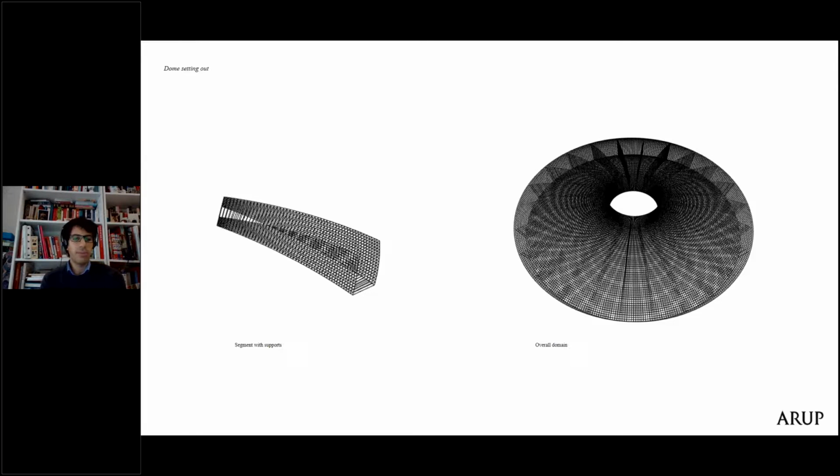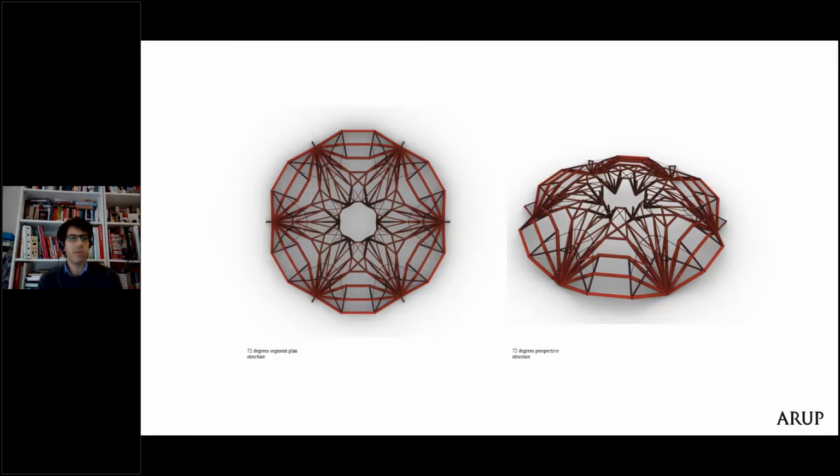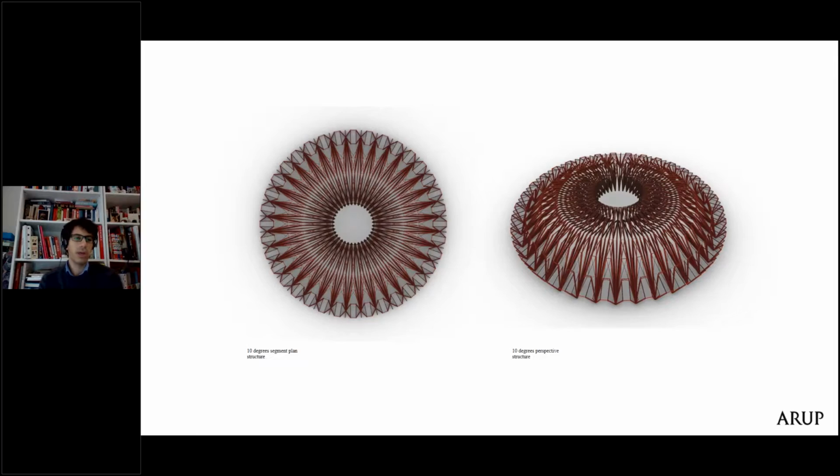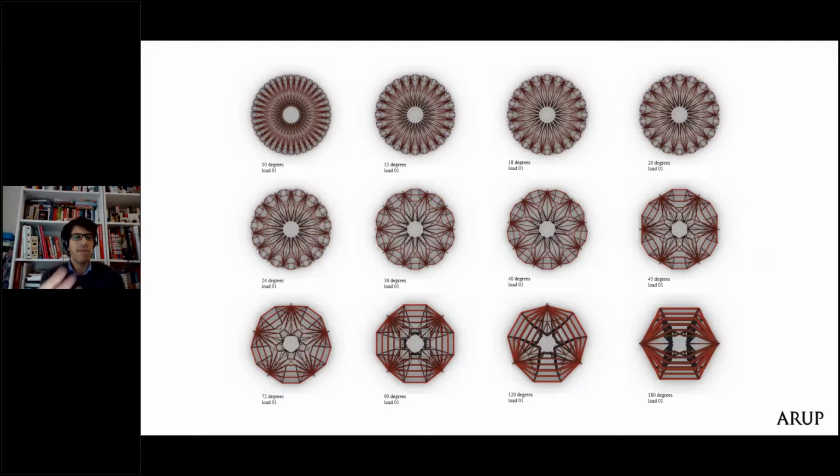And then because Peregrine is embedded in Grasshopper, what we found very interesting and powerful is also to run some parametric studies. So not having a fixed domain, but being able to change the boundary condition, change the application of the point loads in an interactive way. So starting from a very simple configuration with just a limited number of supports to a more complex one when we proliferate the number of supports. And because it's parametric, the load on each one of these members is reduced. Therefore, you actually get viable arrays of different solutions that, even if they are not optimal and buildable as they come out from the plugin directly, you can use as a starting point for a conversation with the architect. And actually, some of these are buildable as we see them, which is, we think, very, very interesting and very, very powerful.